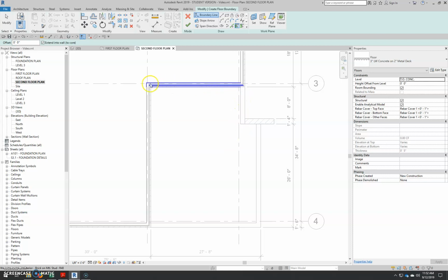And that is because this exterior patio is essentially a roof that you walk on top of. So there is a system of pavers and a drainage system underneath of those pavers. So the floor, the concrete slab, has to be lower than this floor so that you can walk straight from this floor out onto the pavers. So we're going to use the same button again, pick walls.